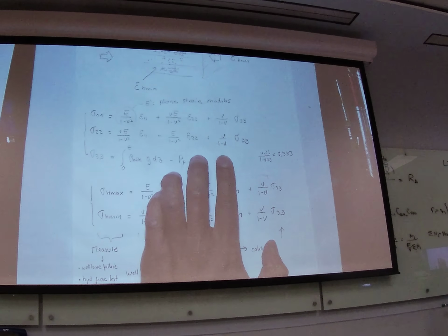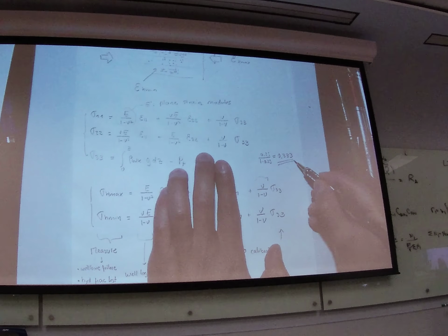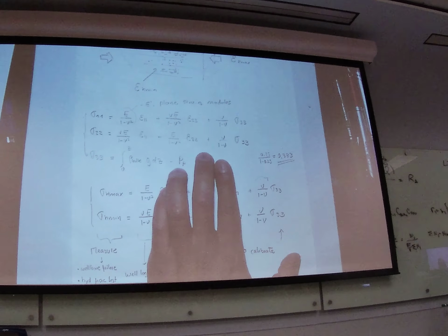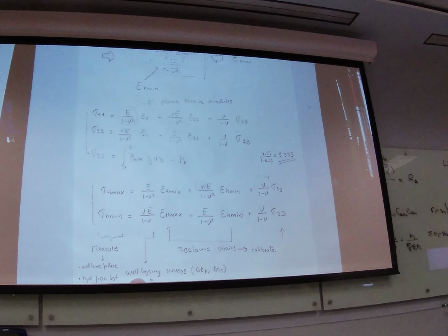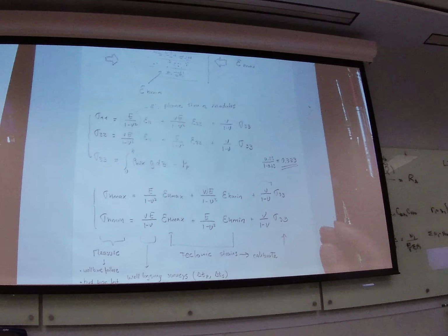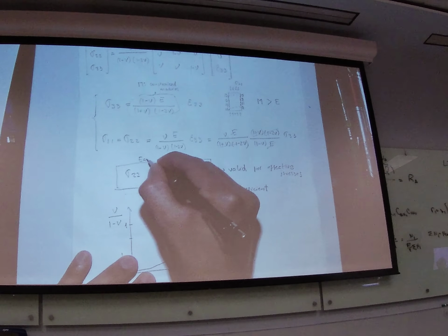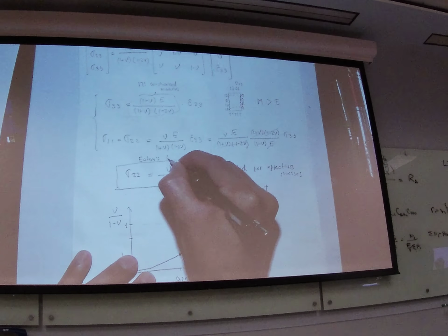So we're going to see two methods to calculate horizontal stress. One is based on linear elasticity, and it is this one, and you see that it gives a similar value to what you were mentioning as Zoback's equation. Actually, this one that uses the Poisson ratio is called Eaton's equation.